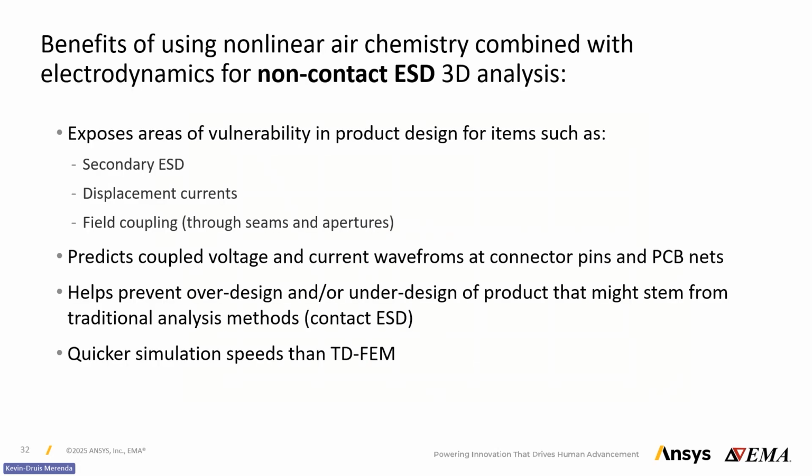So it really helps us quickly expose areas of vulnerability in the design, such as the location of secondary arcs, not just the first arc due to the non-contact ESD gun being applied to the system. We capture displacement currents due to geometry charging up and down, and also charging and discharging, and any coupling of the fields through seams and apertures that could be present, for example, around a button on your cell phone.